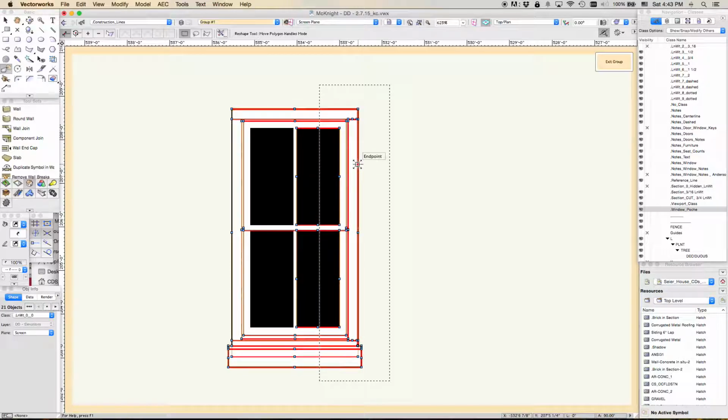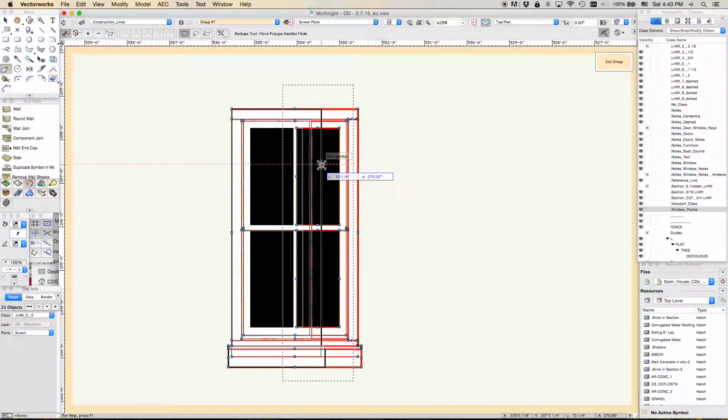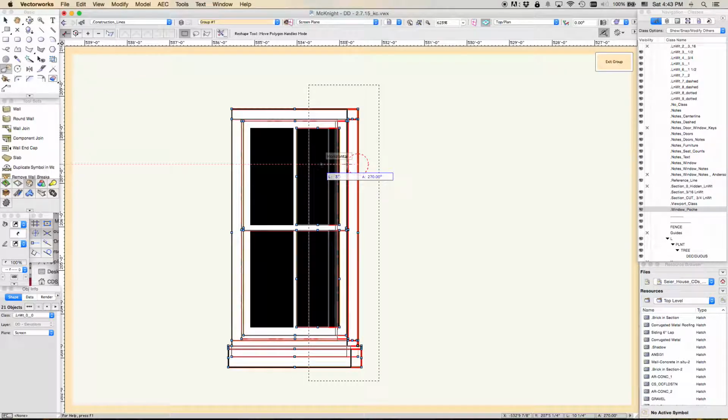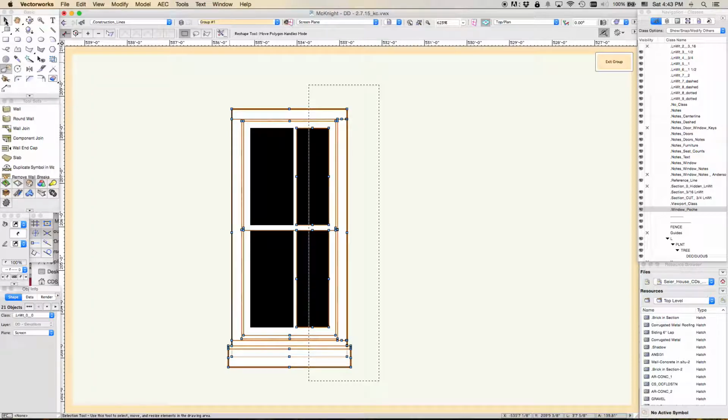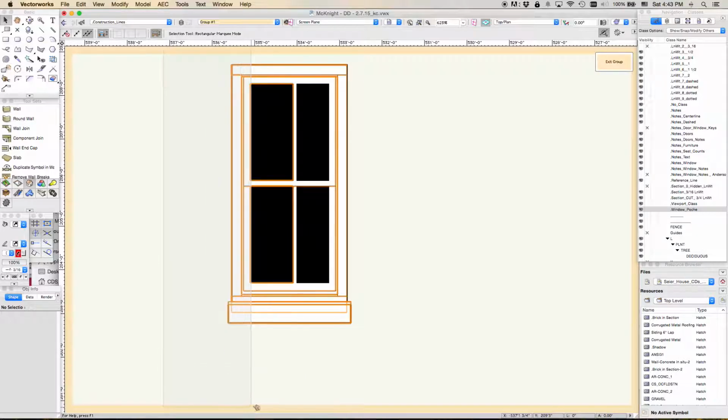I'm going to left click and just sort of pull to the left, and then I'm going to hit Tab, and 3 inches, it goes into that command, and then I'll hit Enter, and it stretches 3 inches. Now I'm going to just kind of click out of it and do the same thing to the other side.